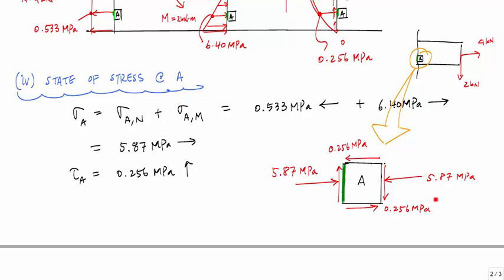And no one says you have to write the equilibrium equations. What you have to remember though with shear stress is that arrows meet in the corners, okay? And this 5.87 MPa, if you write negative 5.87 with the arrow causing compression right here, you actually mean the opposite. So all you need to do is put direction and magnitude for all these stress states. And that's how we draw the representative volume element.